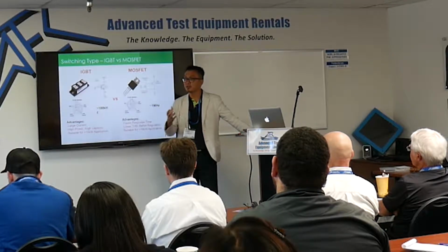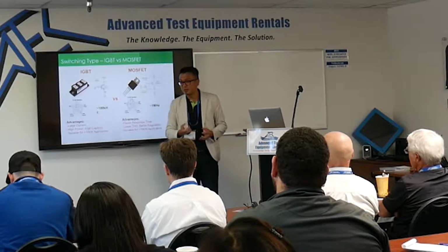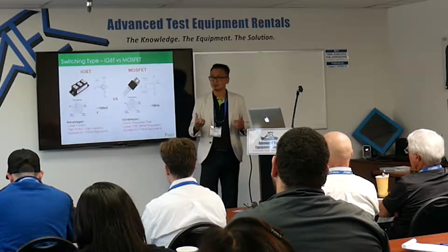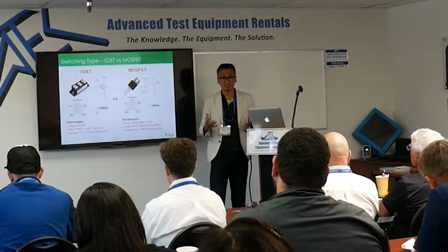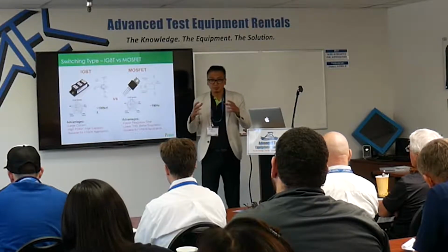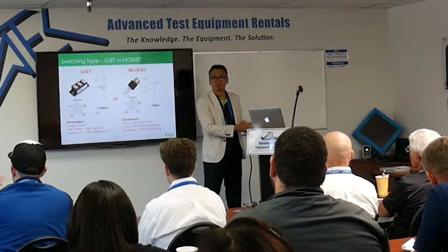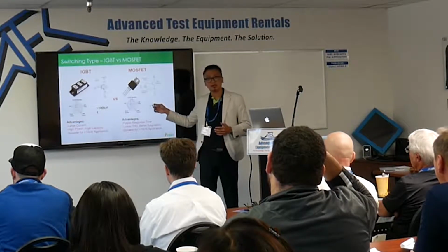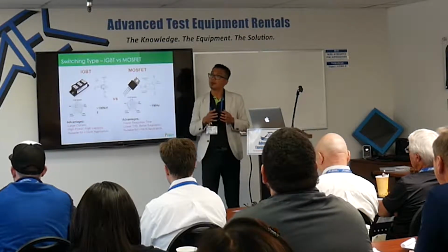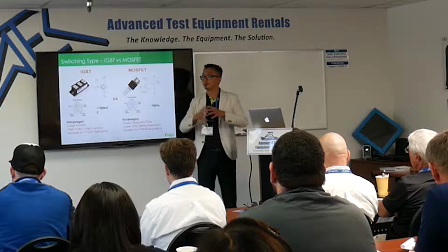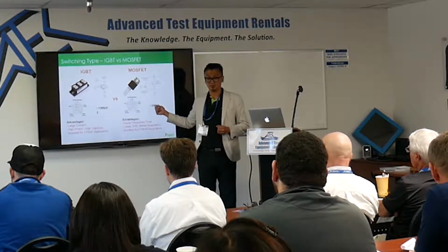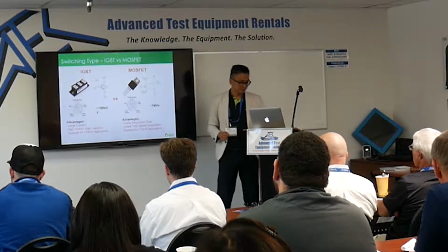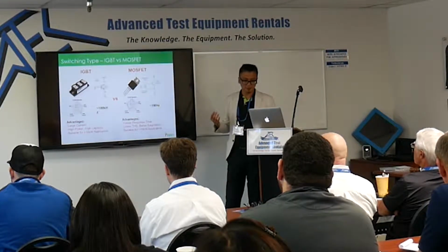So for an EV car, you need very high power, so you need an IGBT. That's a big difference. Like UPS: small UPS, like a home appliance UPS, some use MOSFET as well. So it depends on the size. If you go to a big one, usually go to IGBT. The small one uses MOSFET. Okay. Or when you need a higher frequency.